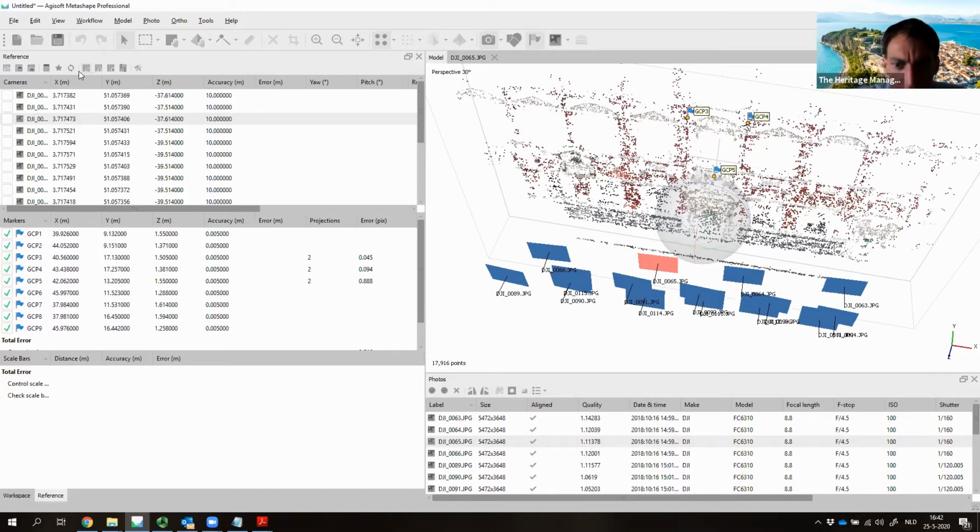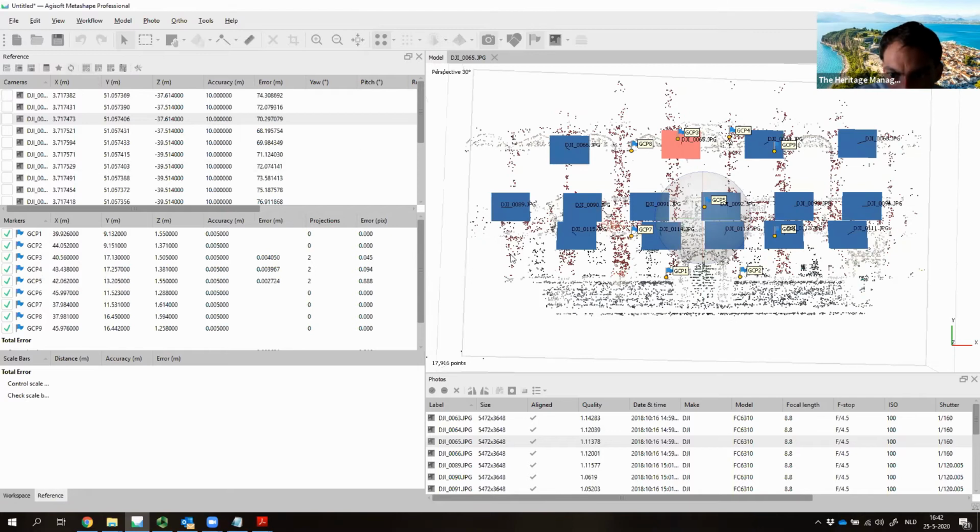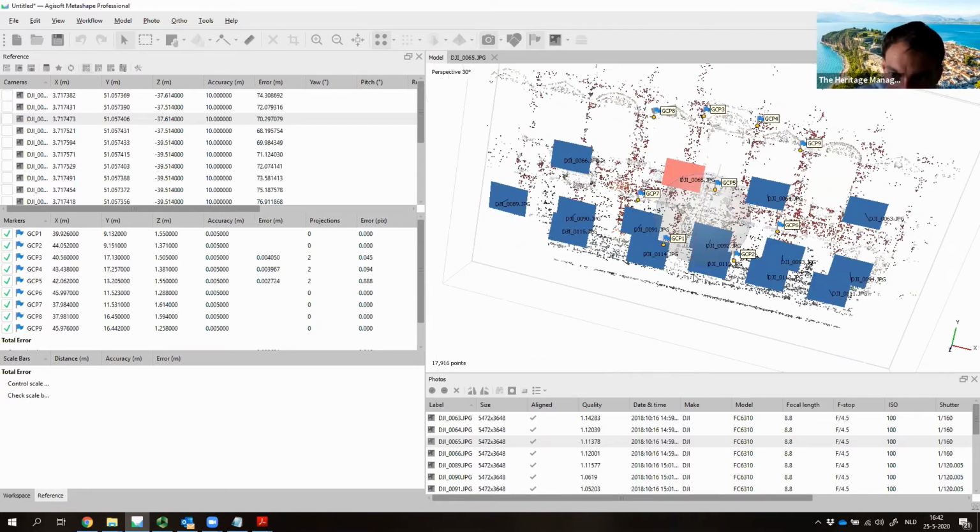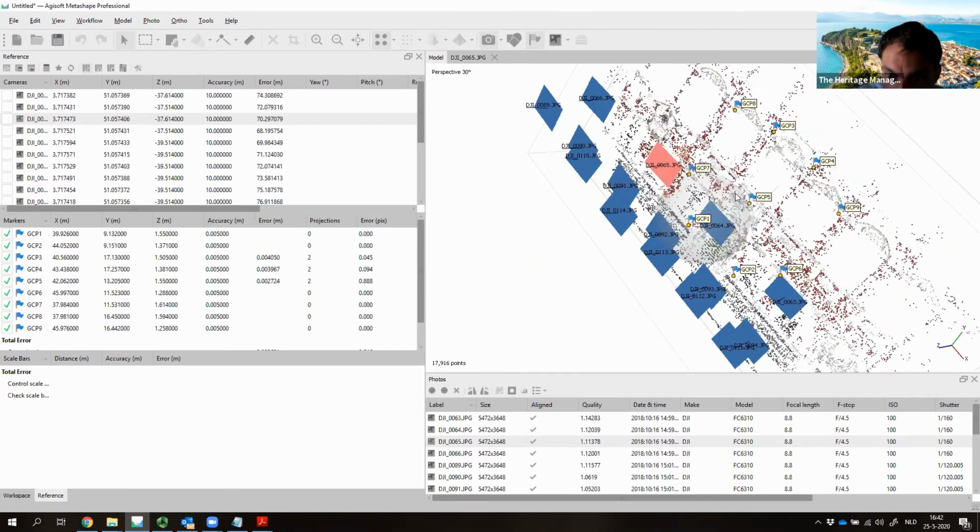The interesting thing is that I already have all my photos aligned, so relatively I already can make a very good estimate of where my coordinates should be right now, because I already assigned multiple points to multiple photos, 3 ground control points assigned to 2 photos.